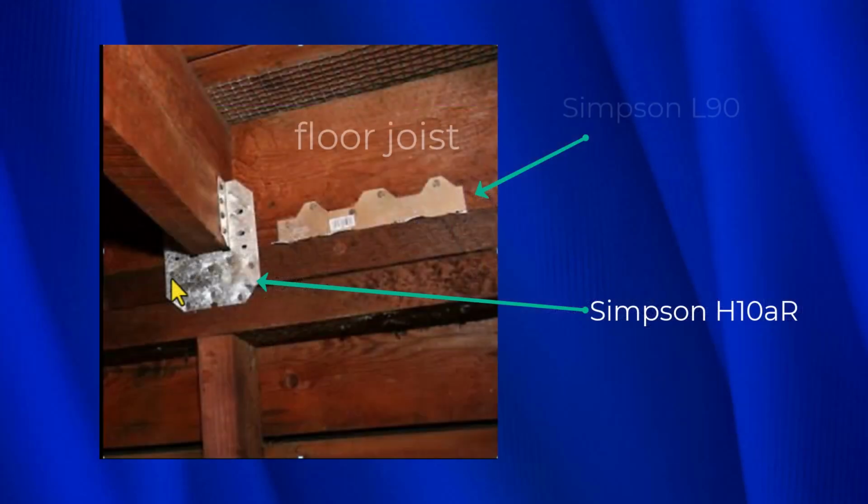Here you see 2 floor connectors. This right here is the top of the cripple wall. Now this floor connector here is called a type E connector in the FEMA P1100, and the way this works is this nail and then this nail and then this nail, they nail into this board right here. And there are some other nails that come down this way and attach to the top of the cripple wall, and that way when the floor tries to move, it goes into this type E connector, and then that goes into the top of the cripple wall, which is what we want to have happen.